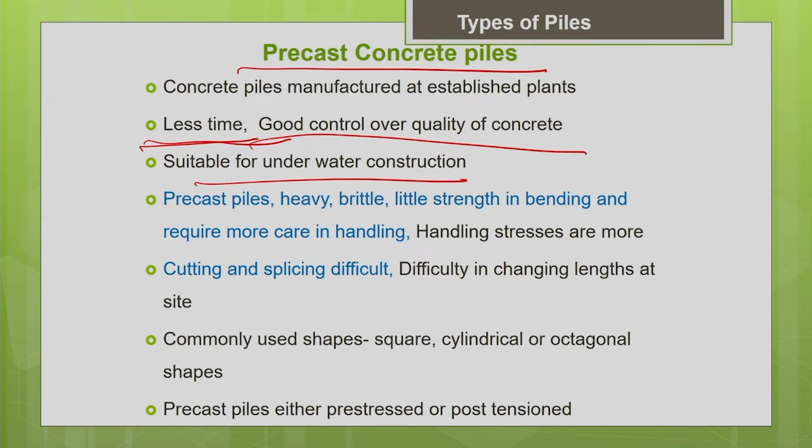So that is why handling has to be done in a very careful manner, and you have to provide some additional reinforcement to take care of the handling stresses. That is very important. For the cast in situ pile, we do not need additional reinforcement for the handling stresses. But for the precast pile, when you design it, we have to add some additional reinforcement for the handling stresses, and we cannot go for a very lengthy pile. You know that concrete is weak in tension and has very poor bending strength. So that is why there is a limitation on the length of the concrete pile also.